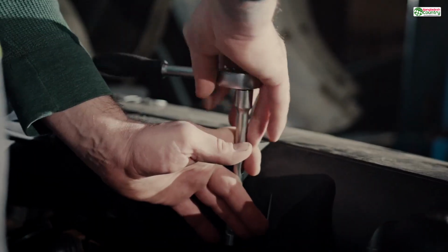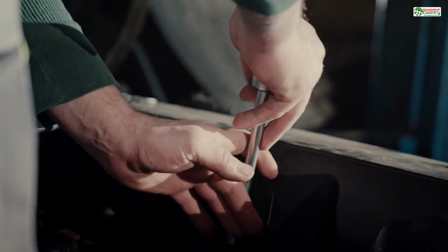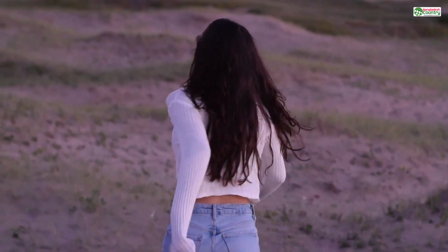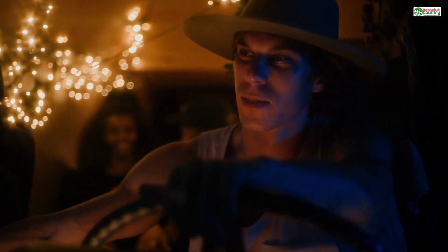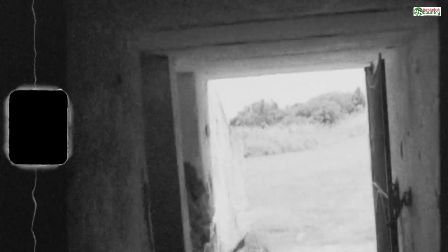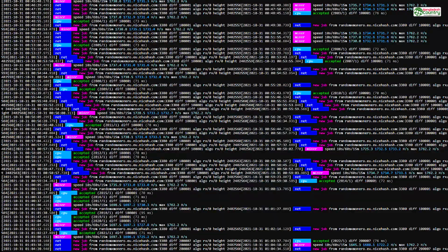Fixing internal geometry is the most hands-on repair. You have to navigate your camera inside the model, like you're piloting a tiny submarine. Once inside, you can see the extra walls and floating bits of digital debris. From there, it's a simple, satisfying process of selecting those unwanted faces and deleting them, cleaning out the inside of your model until it's perfectly hollow and uncluttered.